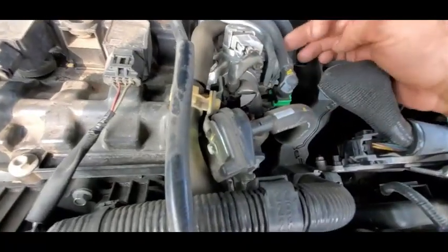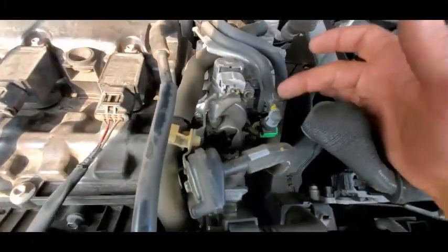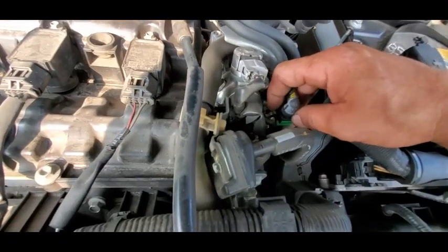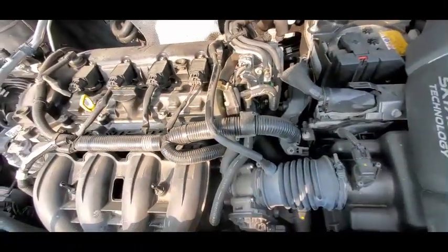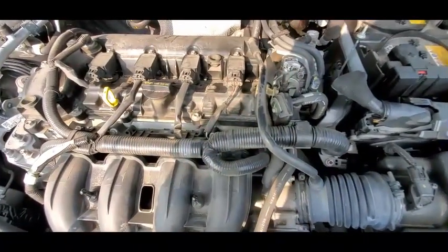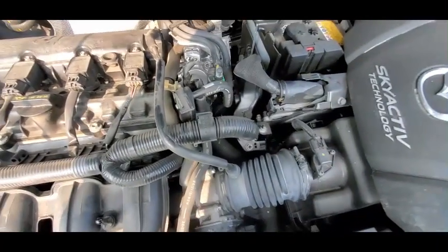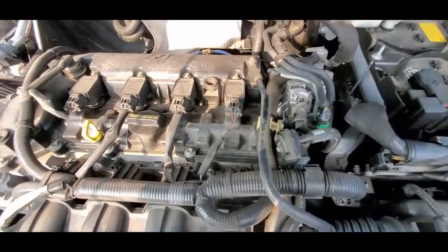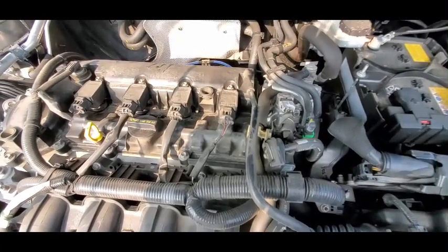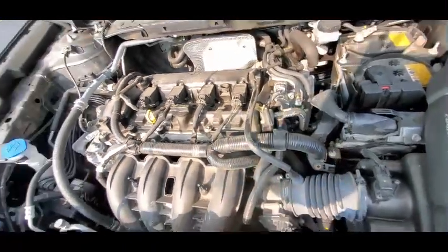All right, so here's our low side supply line to the high pump, because this is our high pressure fuel pump right here. And then here's our low side supply line. So we can tap in right here, adapt in, and get a manual gauge on this just to see what we're getting. And then we're going to be done here. I think we're going to need a pump. I suppose we could try to current ramp it, check powers and grounds to it, but I'm thinking we got a low side pump issue, or they ran it out of fuel and that level sensor's reading inaccurate. One of the two. So let me go grab my fuel pressure set.